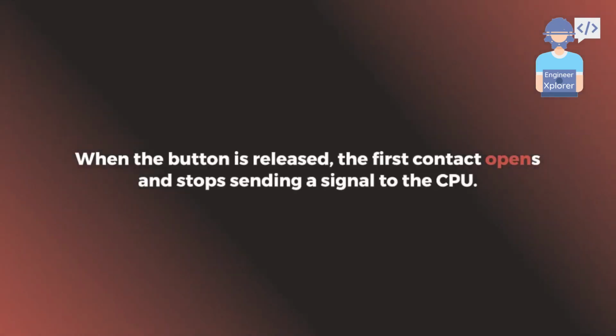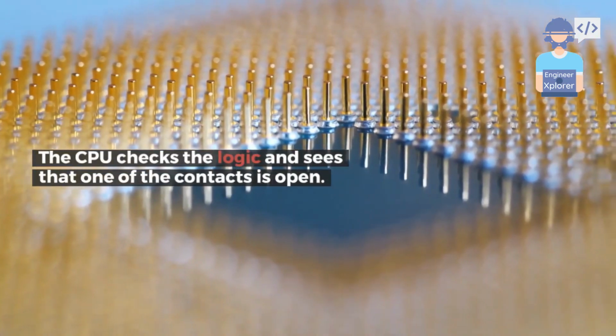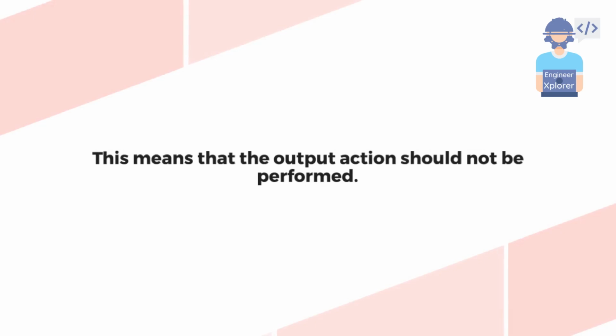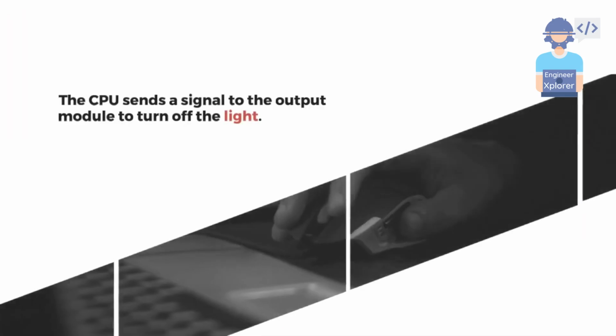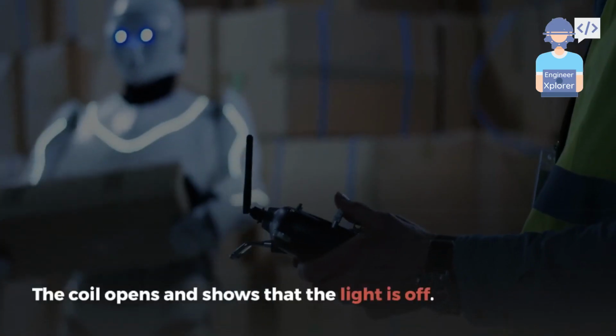When the button is released, the first contact opens and stops sending a signal to the CPU. The CPU checks the logic and sees that one of the contacts is open. This means that the output action should not be performed. The CPU sends a signal to the output module to turn off the light. The coil opens and shows that the light is off.